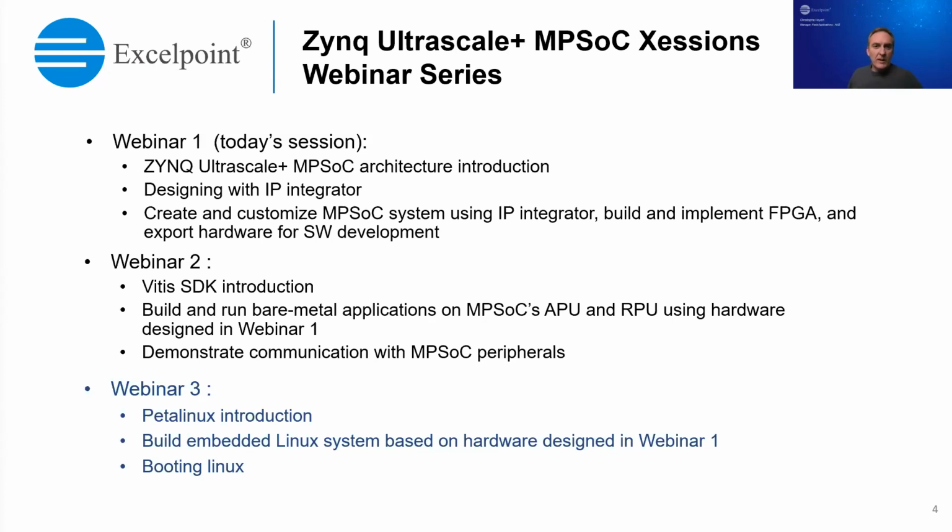Thanks, Jamie. Hello and welcome everyone again to the final session of the webinar series around the ZYNQ UltraScale Plus MPSoC. Just to recap, during the first session, we built an MPSoC system using the IP integrator within the Vivado design suite, generated a bit stream and exported that hardware. During the previous session, we used that generated hardware in the Vitis software development kit, built and ran some very basic applications on both an A53 processor as well as an R5 processor.